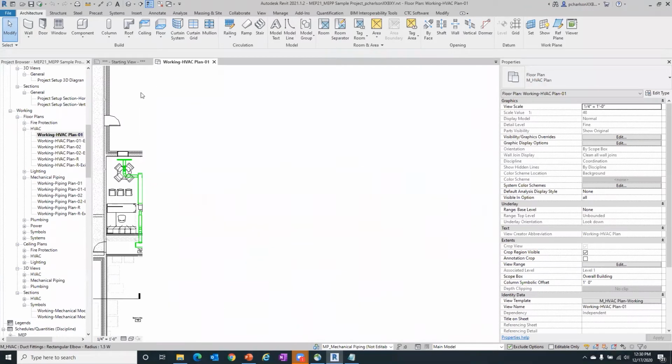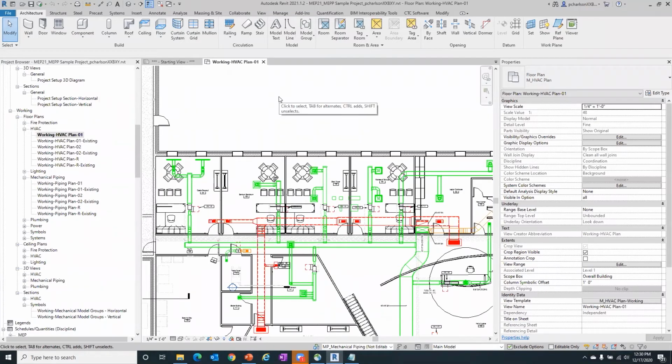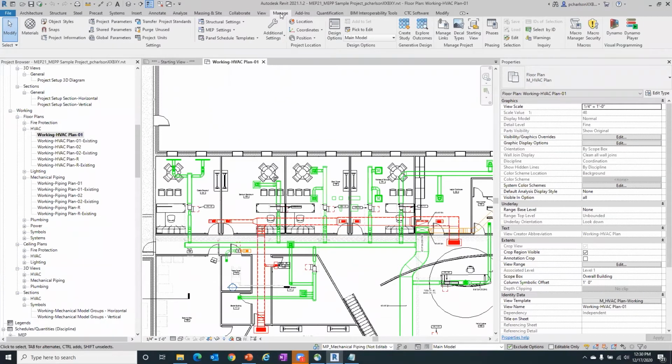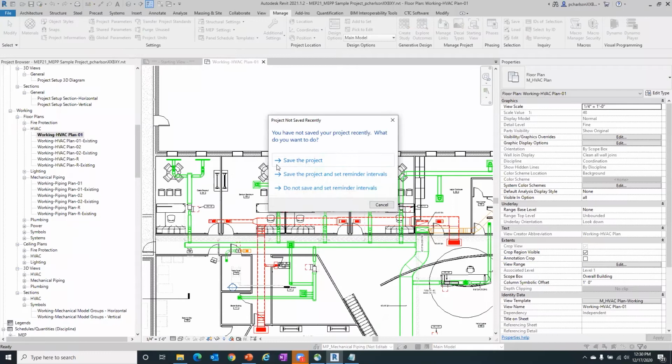And I mentioned getting to your shared parameter file. Up at the top here, if I go to Manage, and in the Settings, I can click on Shared Parameters. You'll also notice that we have the project parameters above that, and the global parameters below that. I mentioned those in the PowerPoint, but again, we're going to concentrate on just the shared parameters here.